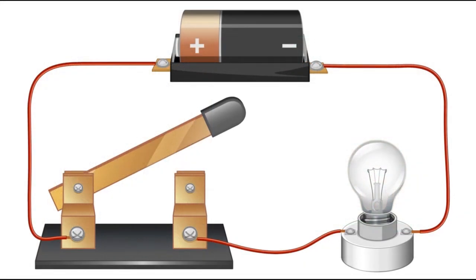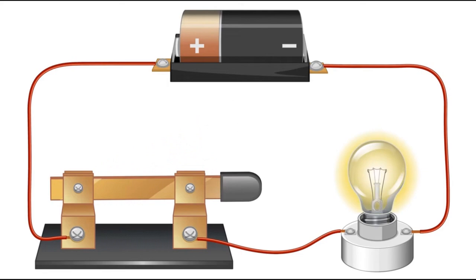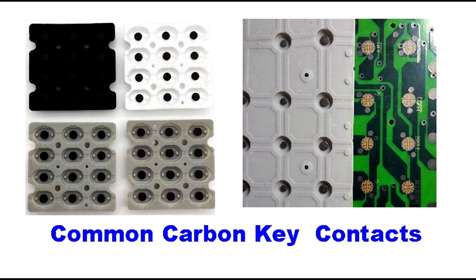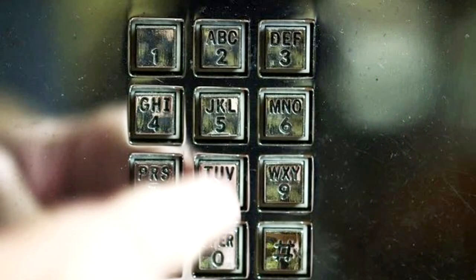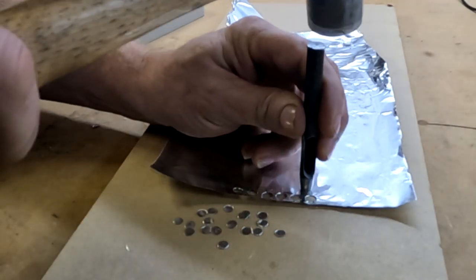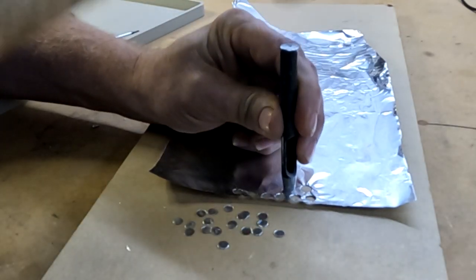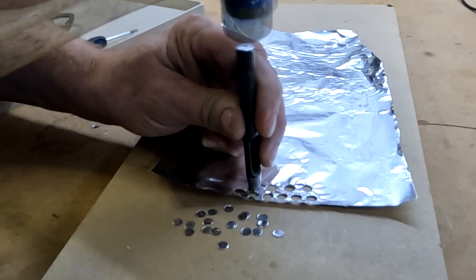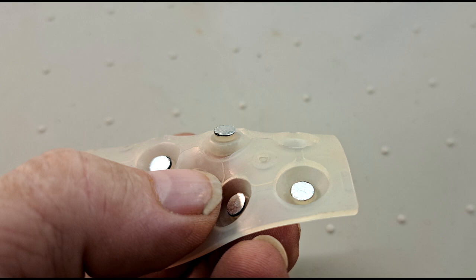The physical contacts for the original keypad buttons do not simply open and close the circuit like a normal switch. There are carbon pads on the bottom of each key. The phone's original computer would measure the passive resistance and recognize which button was pressed. In this case, we need a positive open and closed switch for each button. You will need to disassemble the phone's keypad. You will need to obtain a circular punch the same diameter as the carbon contacts. Make solid contacts out of aluminum foil and then glue them on top of the original carbon contacts.